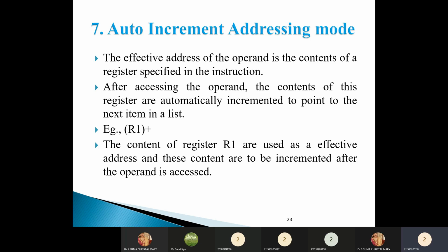In relative addressing mode, the contents of the program counter are added to the address part of the instruction to obtain the effective address. The address part of the instruction is called an offset, and it can be positive or negative. When the offset is added to the program counter, the resultant number is the memory location where the operand will be placed.